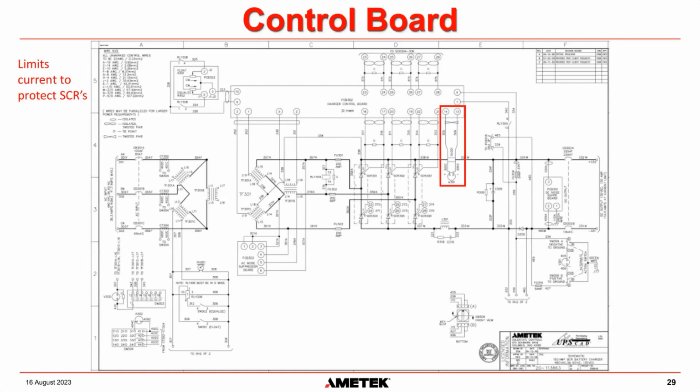So if you see a low voltage on a system, don't automatically assume that it's because the float pot has been set incorrectly. It could be that the system is in current limit. So pay attention to that when you go and see a system.